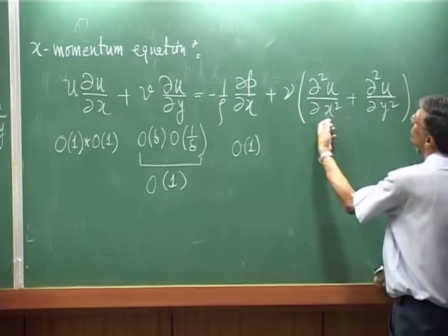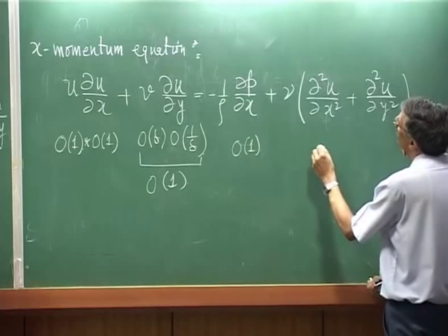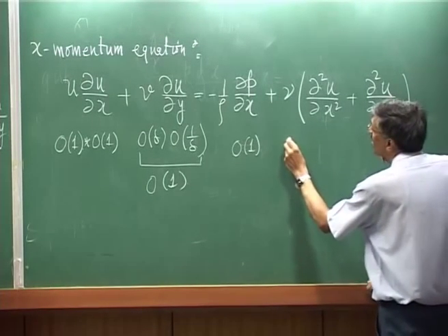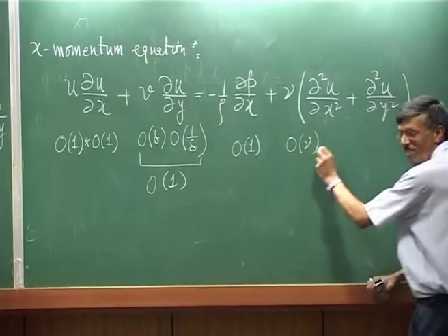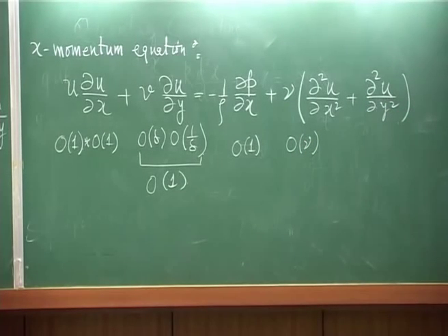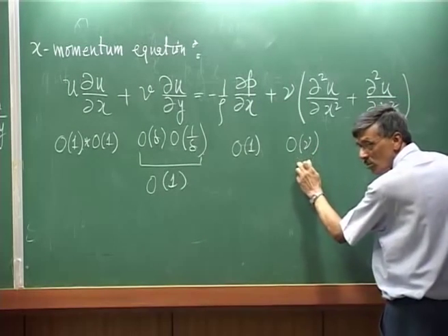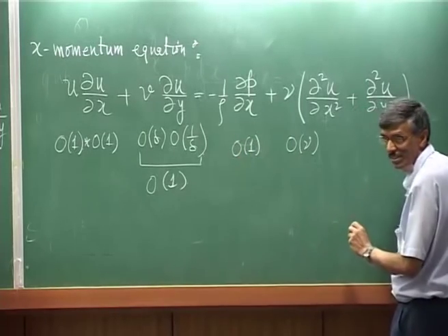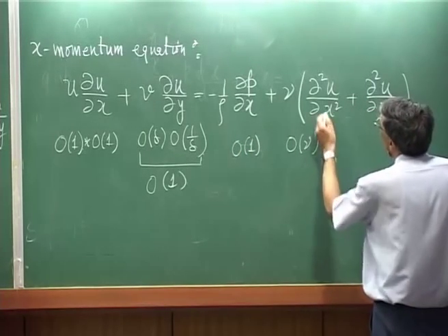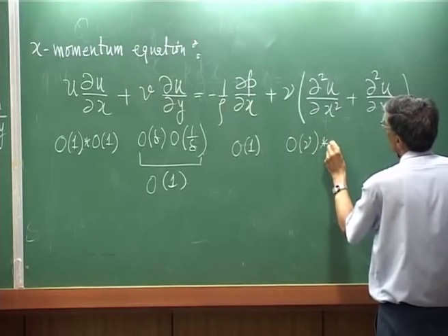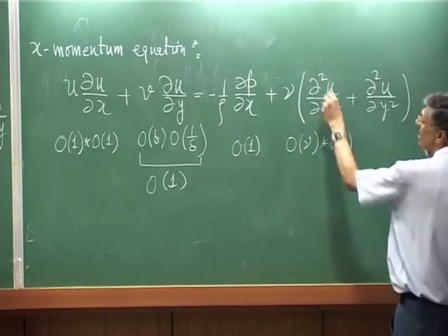Now, when I look at this, what do I get here? Well, I get this quantity. What is this? This is a kinematic viscosity, okay. And when we are looking at this property of fluid, we know that this is a very, very small quantity itself. So, this nu is by itself a quantity which is much smaller than order delta quantity, right. So, what we have here is this is order 1 quantity, right.